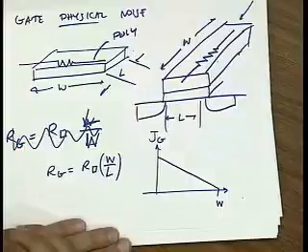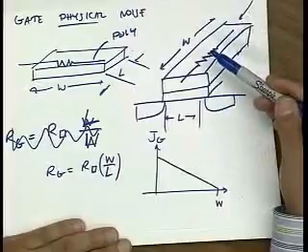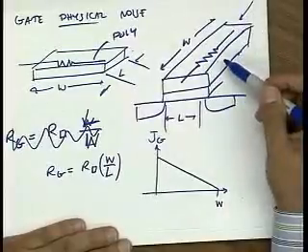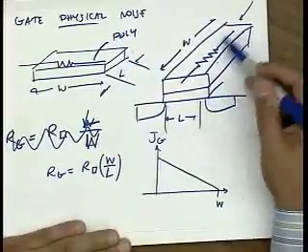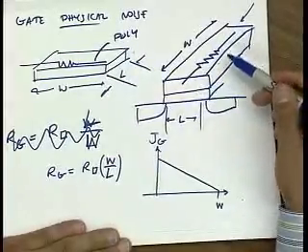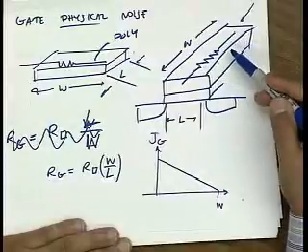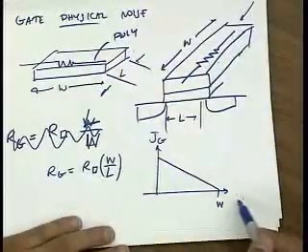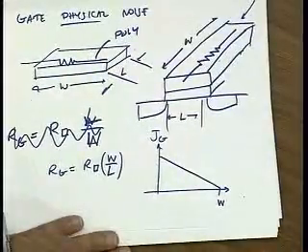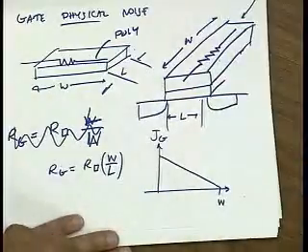In fact, if you do the analysis more carefully, you can analyze this as a distributed RC line, something that we do in 117, for instance. You can analyze this as a transmission line, and you find that the real current distribution is actually exponential. But it's a pretty mild exponential for a real resistor, so it actually does look pretty linear under the approximations of an RC line and a transistor.